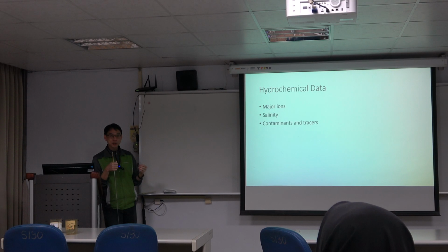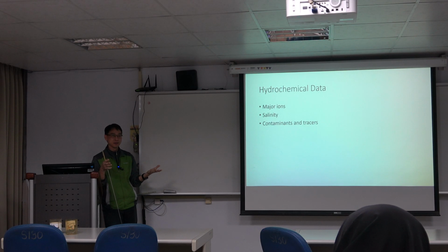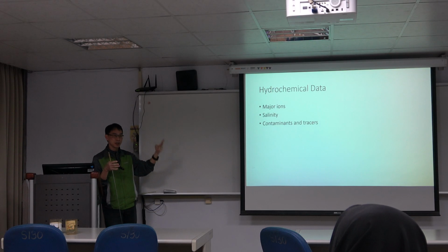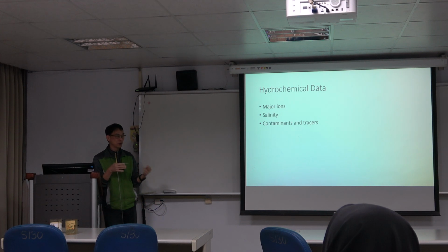Because they want to know if this kind of loop is workable, or if the time is sufficient for the water to move in a loop. But after you get the result, you have already spent maybe 5 years. And commonly 20 years is the operating life of a geothermal system. So you spend 1/4 of the time just doing the test. This is just the test, okay? So it doesn't make economic sense. It does not make sense for these systems.